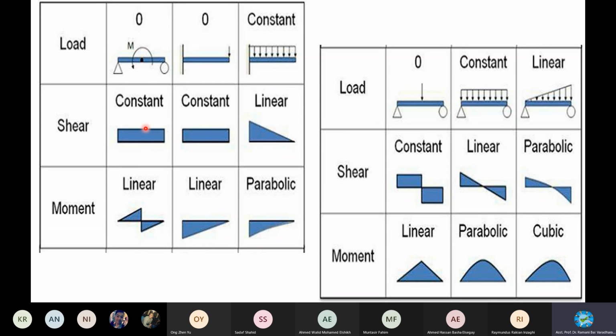You see here the maximum. Okay, it's better I show with another diagram. This one, constant point load. Coming to the cantilever point load, start here. There is a reaction, right? And another thing, the reaction is not causing the moment here, because it's fixed end. Note this point, underline this word, because it's fixed end, there will be a fixed end moment.